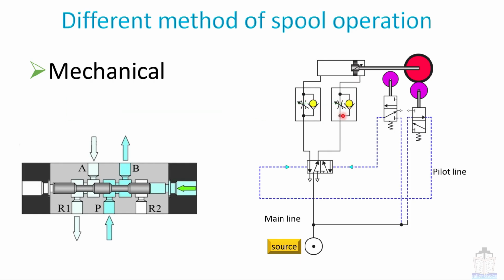Airflow occurs this way, meaning by lifting the valve, and it goes all along this way. Opposite flow of air is restricted by this valve and it is allowed to pass only through this restrictor. And this symbol shows that we can adjust the flow of air passing through this valve, and hence we can control the movement of this piston.